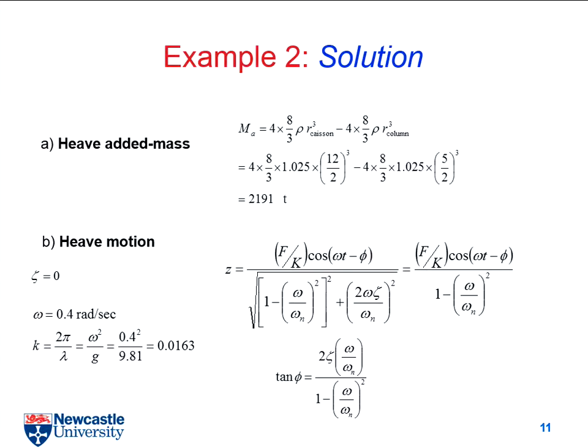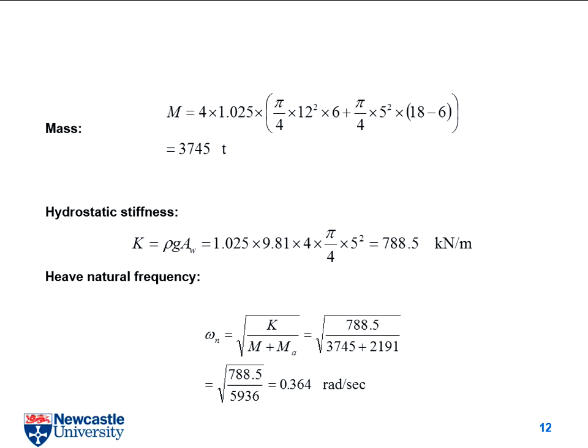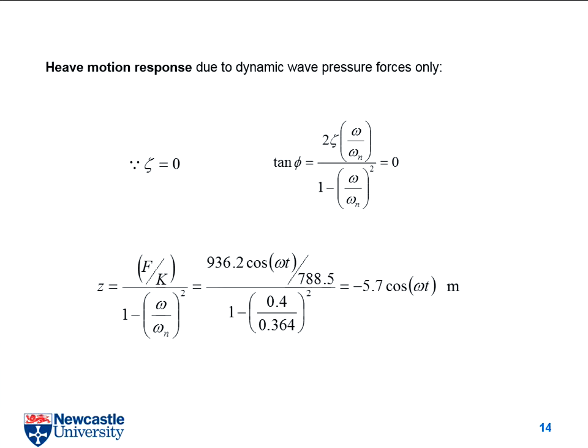So we found the natural frequency, yeah, we have finished already. Well, again, because we don't have the damping force, and the damping ratio is 0, so the phi is 0, so we just have omega t, right? And we know F, we know K, we know natural frequency.